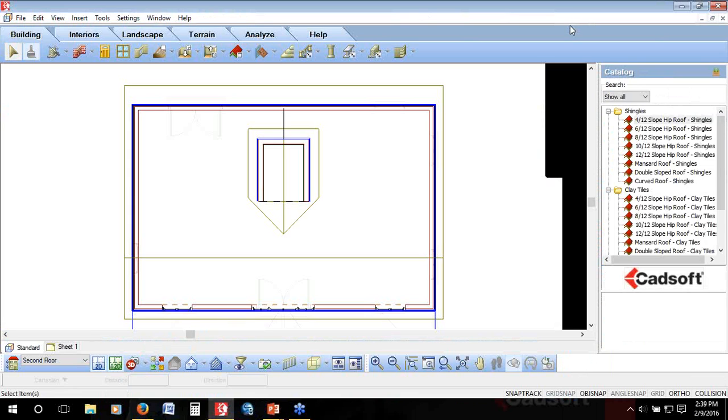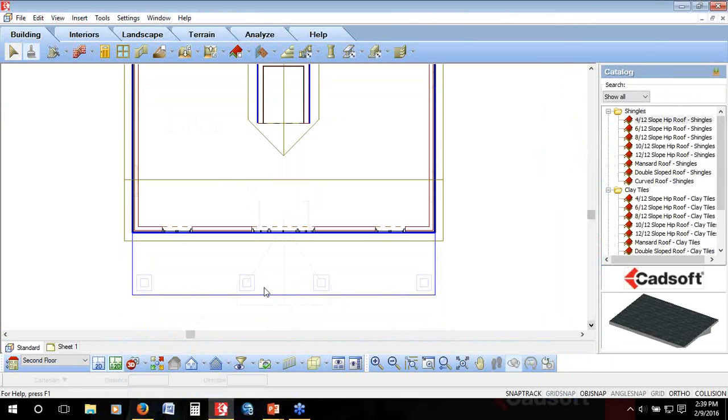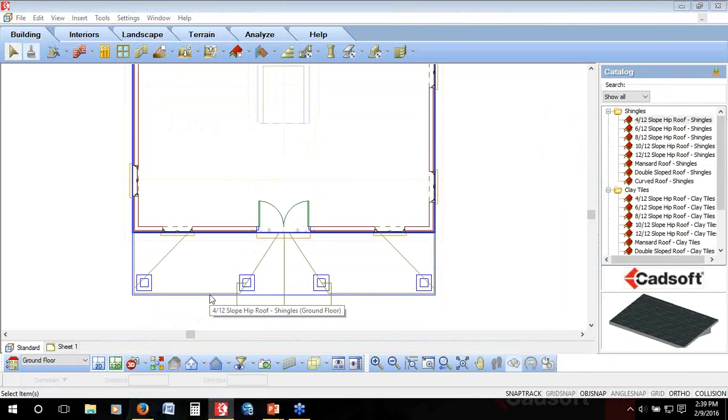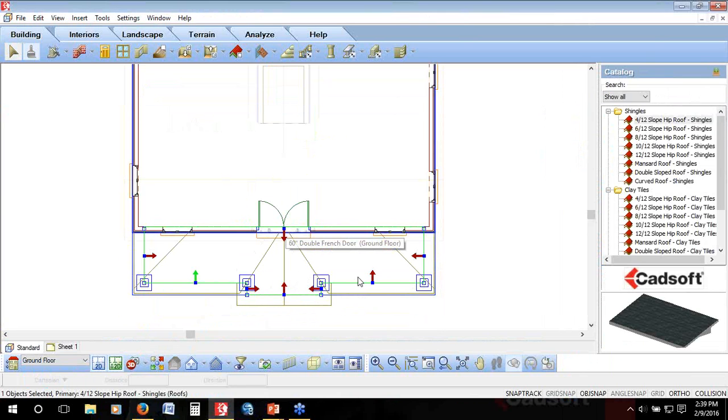And if that's what you're describing, I'm going to go to the ground floor here, where we had the roof, with these being our fascias on the ends. This would remain our hip portion at the house, and these ends out here would be our gable. So it would be just the opposite. Where you would put the gable is where you wouldn't hang a gutter or an eaves trough. So just remember that: if it's opposite, I wouldn't have a gutter or an eaves trough out here.